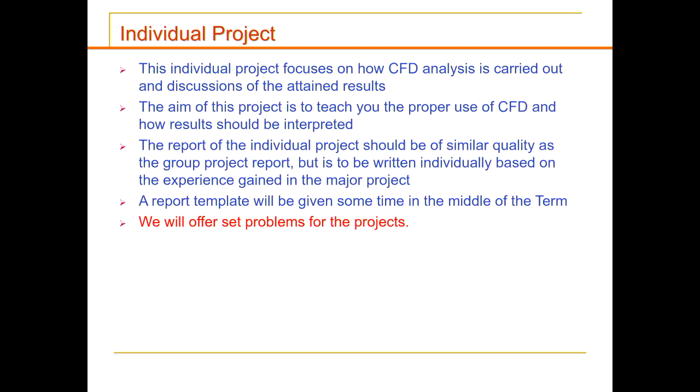Because anyone can produce a CFD result, since they are just color pictures at the end of the day, right? You can go out there, use software, and give me a very nice picture. But if it is a wrong picture, I'll just throw it back to you, because I know by experience that it doesn't make sense. So you've got to make sense of the pictures that you produce and how you analyze them. This is the target at the moment.